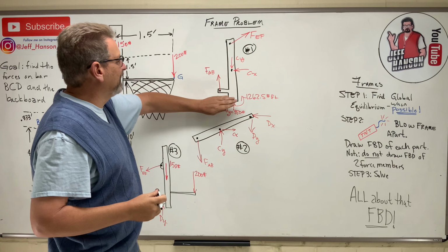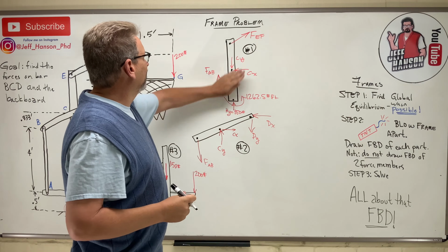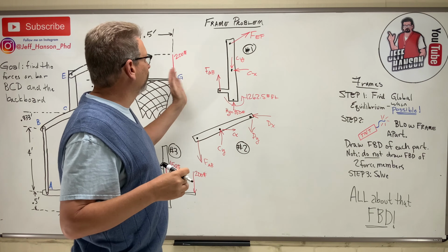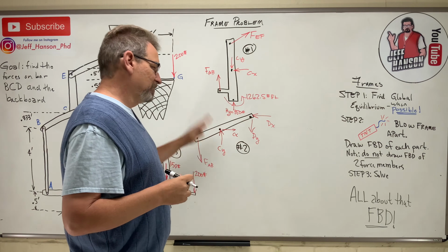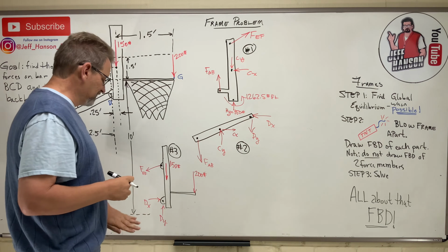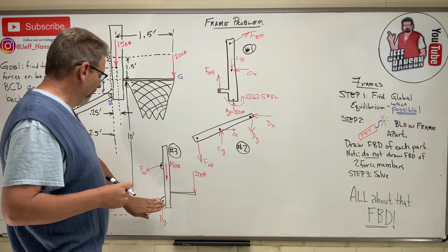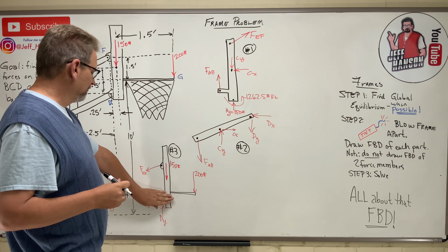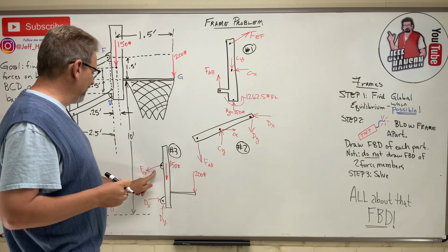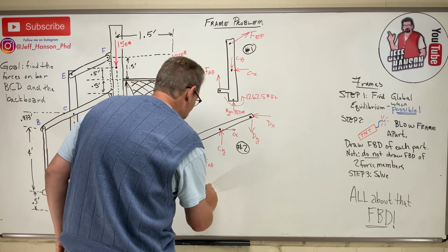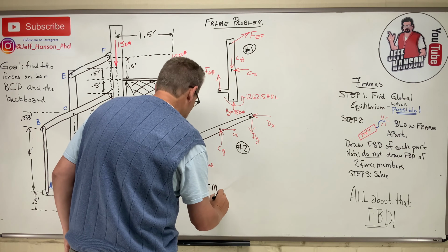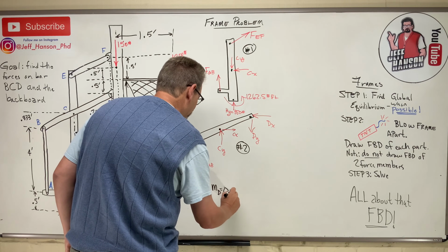Okay, if I take the moment here, I've got unknowns, no, that doesn't work. I can't do this one, no, that doesn't work at all. If I take the moment there, too many unknowns. What about this guy? Take the moment at D. Ooh, take the moment at D. Yes. And I'm going to get FEF, right? Let's start there, okay? Summing the moment at point D, okay?